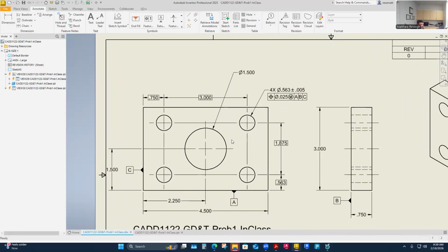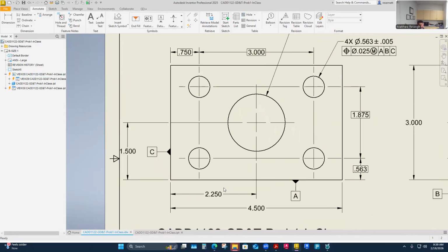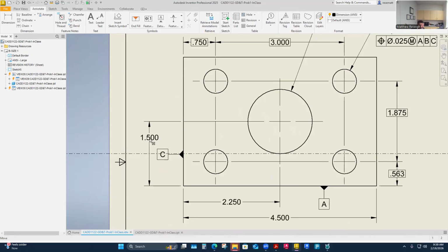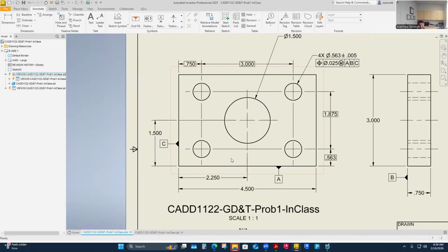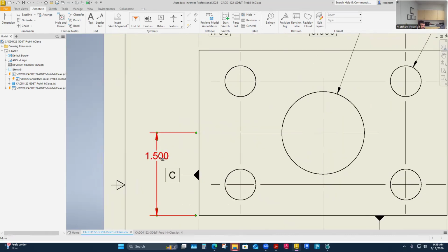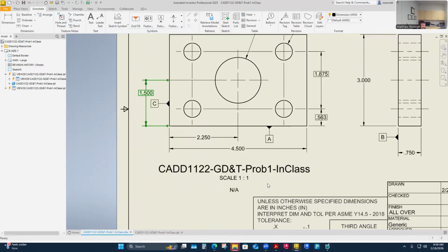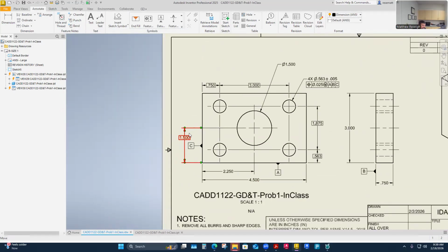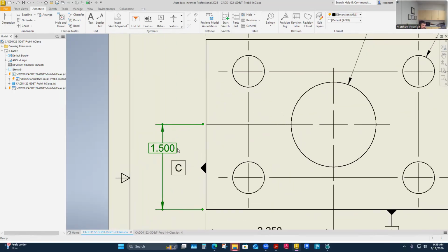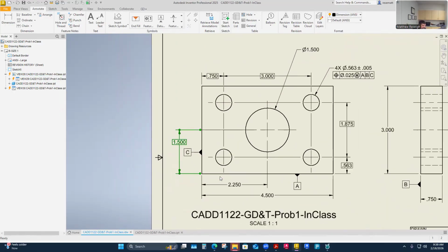So let's do the other hole that way. And it's about the same concept here. So my hole here, I'm locating, okay, great, this is off datum A. Oh, great, this is going to be a basic dimension then, because I'm locating from a datum. So I'll go ahead and get it away from having to apply this tolerance block, box it around, protect it, fence it in. It's a theoretically perfect dimension.